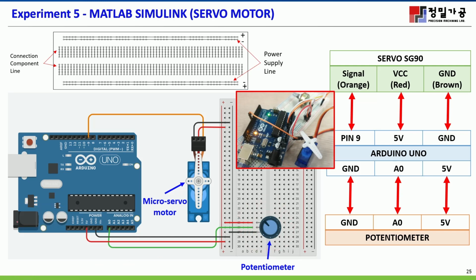Some students maybe still connect wrong, so remember in here, remember this kind of breadboard, these 5 points in here are connected to each other. This one is not connected, like this one is disconnected in here. So basically this one is connected, this one is connected, but this one is not connected through all like this, not like this way.